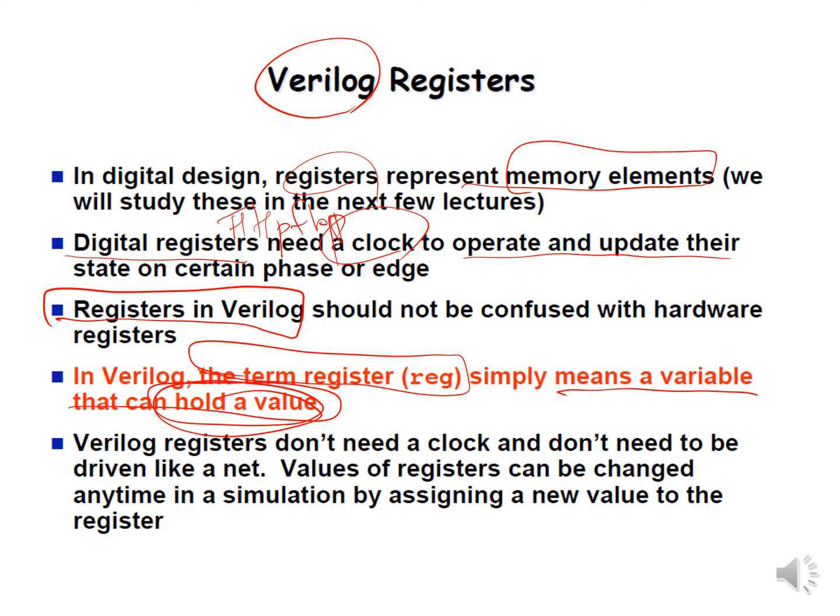Why do we need this kind of definition in Verilog? By having this kind of definition, we can assign values sequentially. Let's say A goes to B, B goes to C, and C is assigned to D. To evaluate variable D, you need to evaluate the first line, then the second line and third line, in this kind of sequential order.